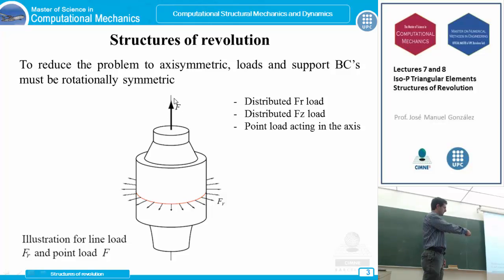So even if the point load is not on the axis, we could treat this non-axisymmetric problem as if it were axisymmetric, using this Fourier development. So this is the set of axisymmetric loads we can have in this axisymmetric problem, just to consider it as if it is. If it's not, we could simplify or just treat it as a 3D problem anyway.